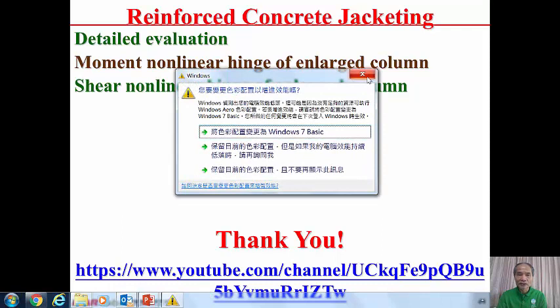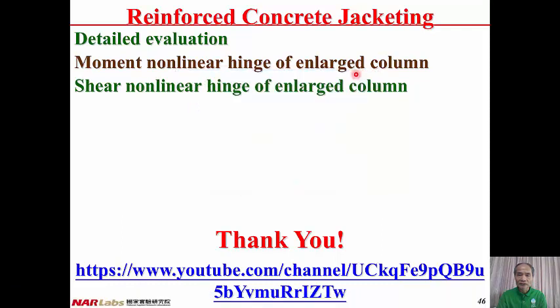And in this lecture, we demonstrate how to calculate those hinge parameters for moment nonlinear hinge and for shear nonlinear hinge. And then this information is necessary for detailed evaluation for the structure after reinforced concrete jacketing, after retrofitted with reinforced concrete jacketing. And we use a column as an example to demonstrate how to assign moment nonlinear hinge and shear nonlinear hinge.